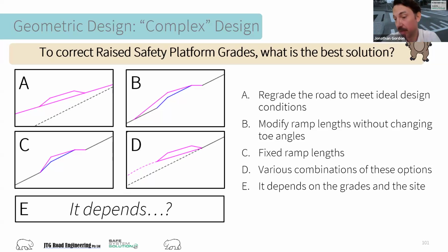Yeah, it does. And I guess in a similar way that you can resolve grading issues for a raised crossing, you can consider minor regrading of path areas or crossing areas without a raised safety platform there. But that's quite extensive work. And if a raised safety platform would be appropriate, then yeah, certainly gives you that additional opportunity. It's a great pickup, actually. Good comment.